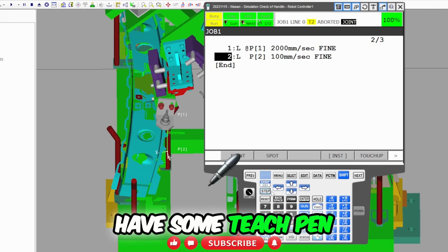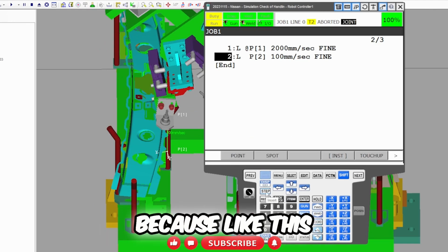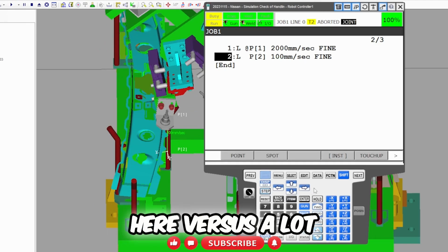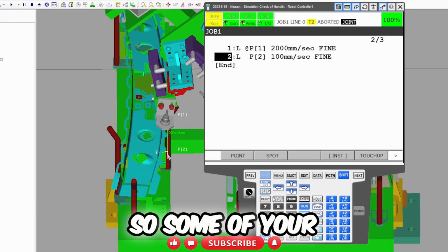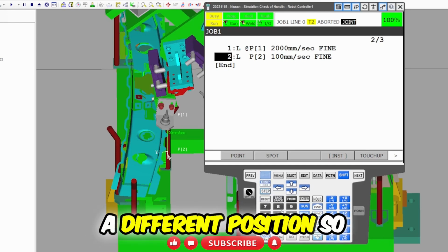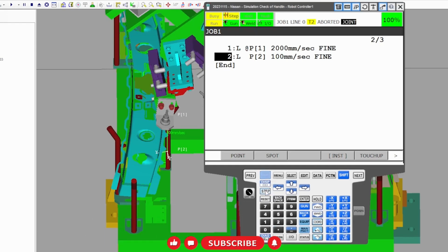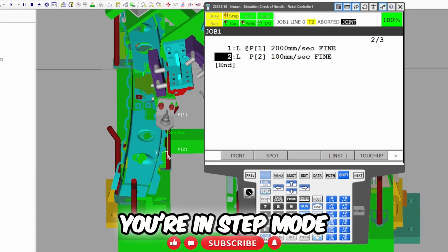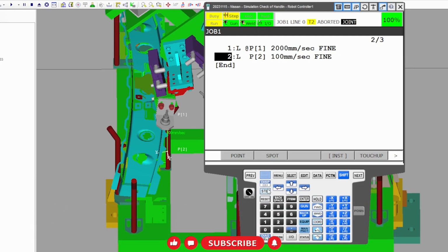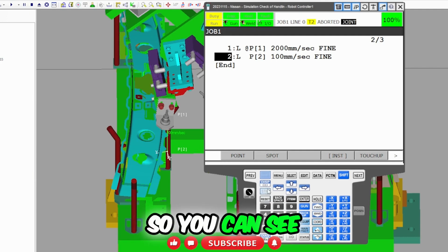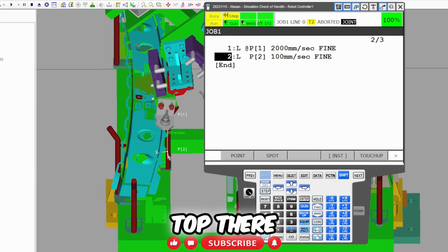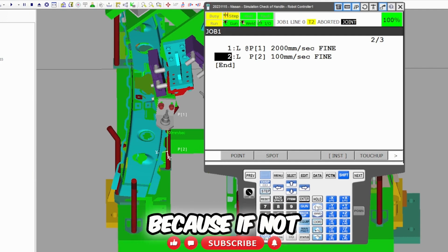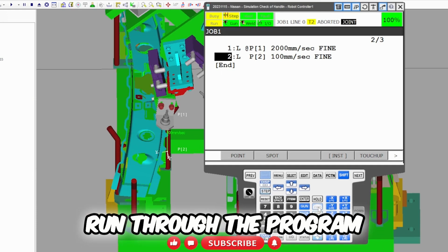Yeah, so you might have some teach pendant things that are a little bit different, because this step button is over here versus a lot of times the step button is over here. So some of your buttons might be in a different position. So shift, step. You can see up here at the top, these are your indicators, whether you're in step mode or not. You can see it toggling at the top there. So we want to be in step mode, because if not, it's going to just run through the program.